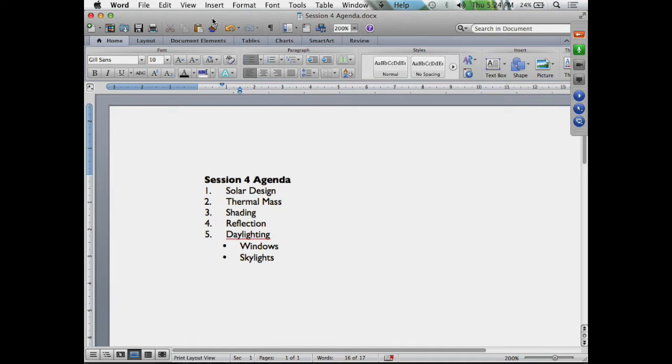At a high level, what we're going to be really thinking about today is a lot of the aspects about how the building is affected by the sun, continuing with that. And then especially looking at the whole issue of how light is infiltrating the building and what we can do about that. So the sun as a source of energy beating down on the outside of the building is giving radiant heat to the building, and the building surfaces absorb and re-radiate it. That's one piece of the equation in terms of what's going on.